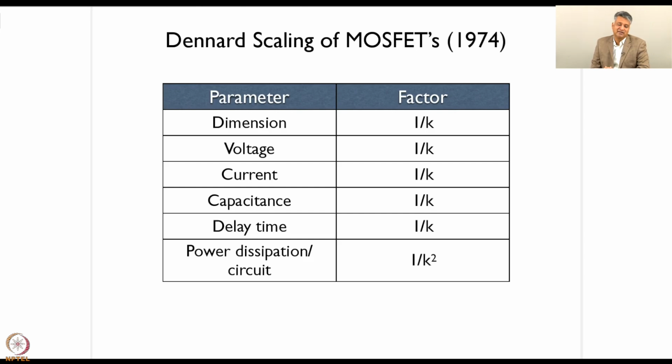Now, while we are still continuing to push the limits of Moore's law by packing more and more transistors by reducing the feature size, as I said, today's technology can produce transistors at 3 nanometer sizes. Dennard scaling is already broken because we cannot continuously drop voltages, currents, and so on as we drop the dimension. The reason is that to identify the binary states of 0 and 1, we need a certain finite voltage, and that voltage limit has essentially been hit.